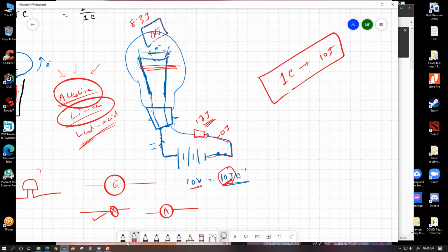So in this case, we have two resistive components. One is the filament, another is the resistor. Automatically, this 1 coulomb charge would know how much energy to spend where, so that once it is out of the last resistive component, which is this point, it will have no expendable energy left. What I was choosing as random numbers is that if that 1 coulomb charge gives up 8.3 joule of its electrical energy in the filament, then it's going to flow through all of this path holding on to 1.7 joule of energy, then give up 1.7 joule within the resistor, and as it comes out of here, it comes out with 0 joule of expendable energy.